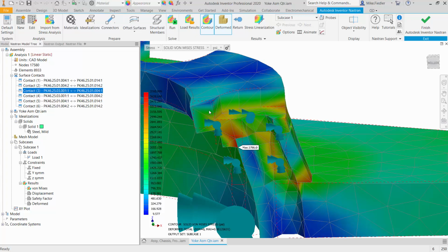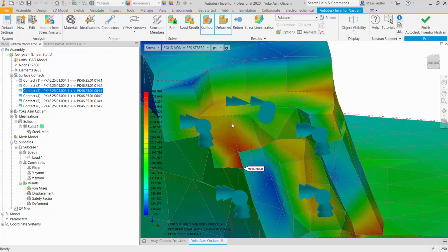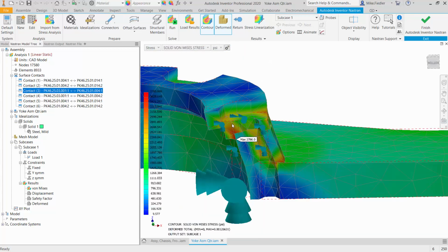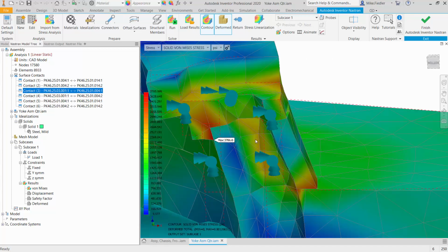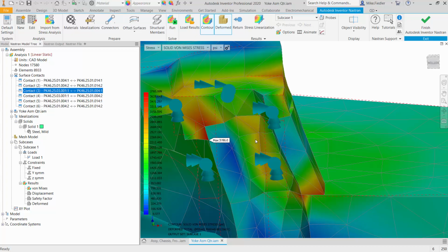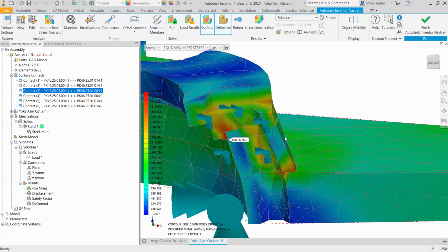plate where it gets bolted and the spacer that's there, kind of in one of the notches of the geometry. So this might be one of those instances that I was talking about in one of the prior slides, that maybe we simplified the geometry too much. We can also see high stresses right here. Would this actually occur in reality?